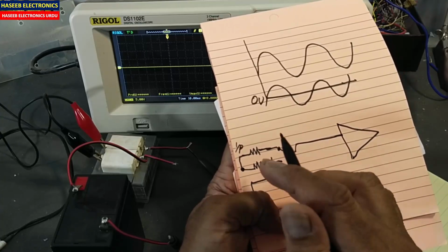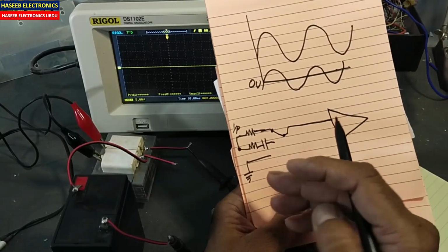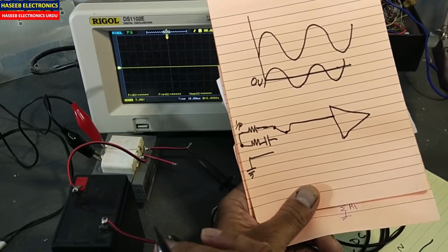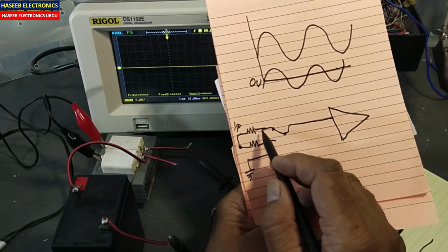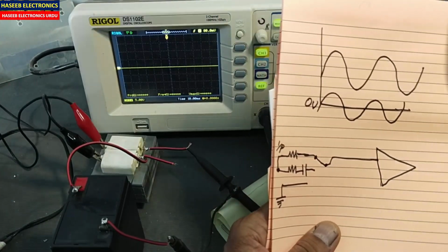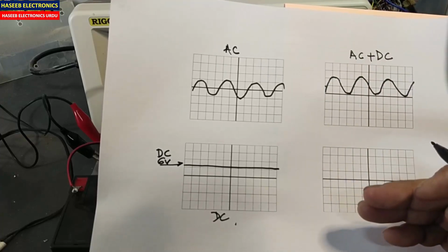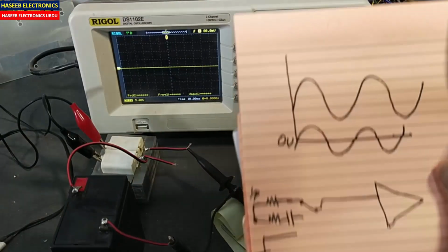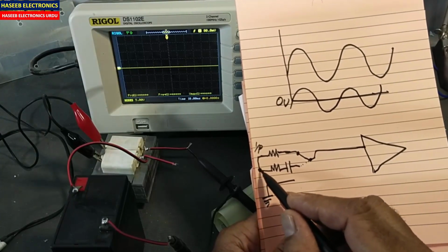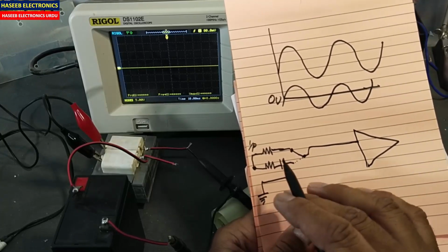Either it is DC, it is AC, it is pulsating DC, it is half cycle, positive half, negative half, if it is sawtooth, whatsoever, it will allow DC plus AC, all signals, to pass. And we will see the signal with elevation or in the negative area. When we connect to AC coupling, at that time it will allow just the AC signal to pass.